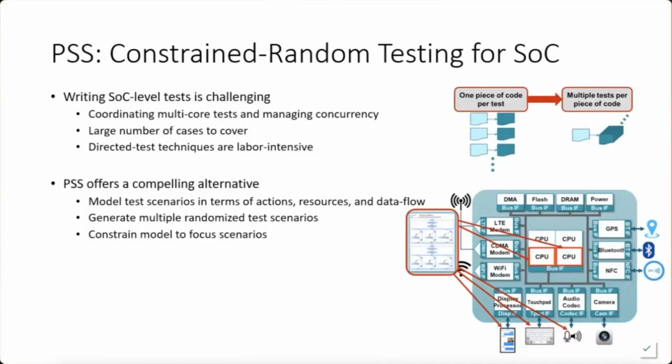Now, creating these bare metal embedded software tests is actually quite a challenging proposition. In today's complex SoCs, there are lots and lots of cases to exercise, and with bare metal C tests, we typically only have directed testing techniques for test creation. Moreover, we need to use all the processors in the design because they are, after all, part of the design. We need to run them and deal with the concurrency and parallelism with these to truly exercise the design's behavior.